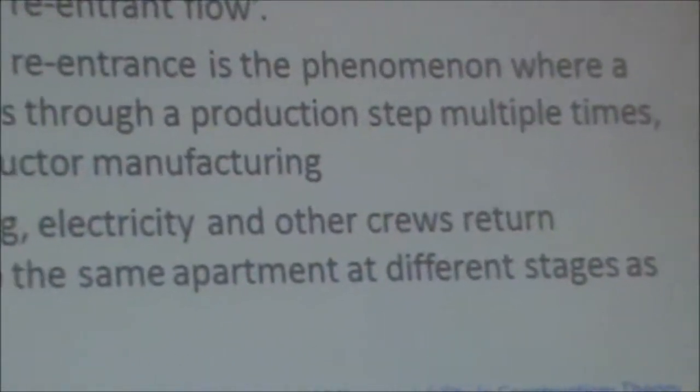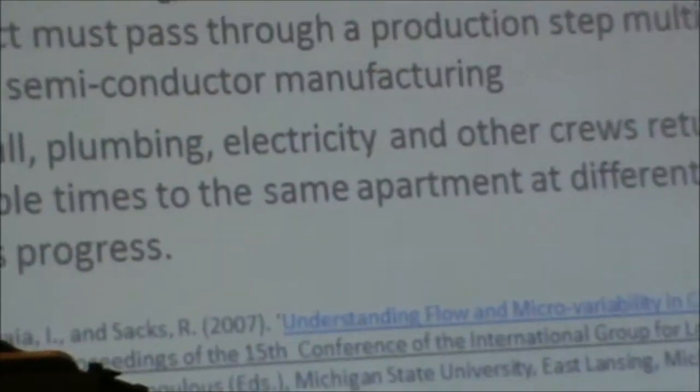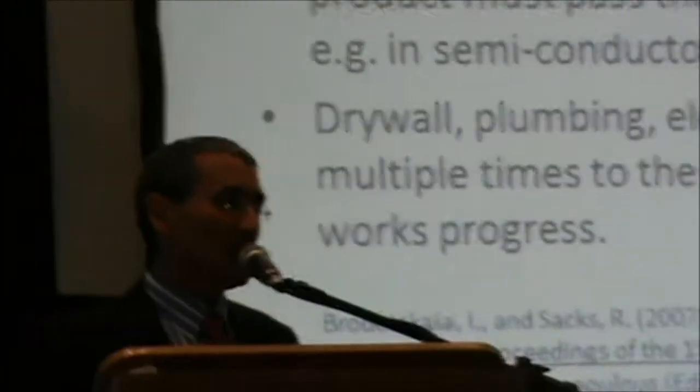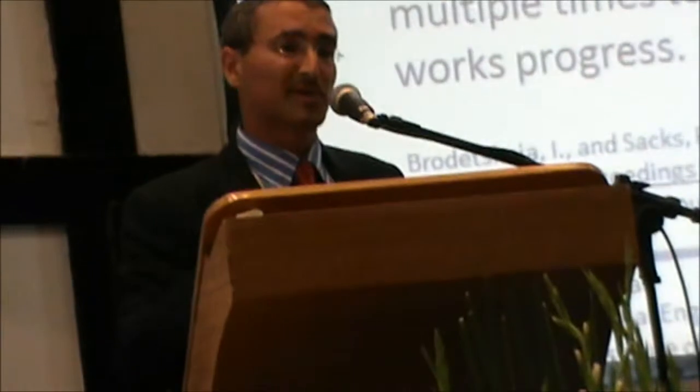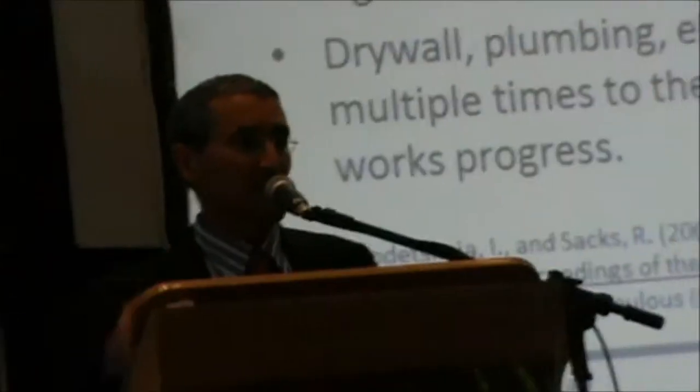Electrical workers put in some pipes, they go away, they come back, they do some wiring, they go away, they come back, they put the sockets on the wall and so on. So there are many similarities. Especially drywall, plumbing, electrical works and so on have this typical behavior. Now what that does, and I'll show you that in a moment, it means that when teams begin work, when the drywall team works up a building, as soon as some spaces become available for closing the drywall, then the team that began goes back to where they began. And that's fine, because we want them to close out. But what happens then is that the electrician and the plumber and the others have no work. So you'll see them starting in cycles of interrupted flow of work.